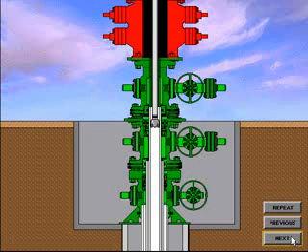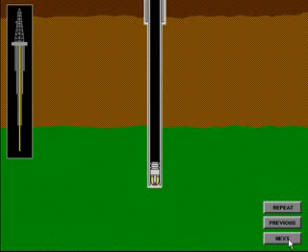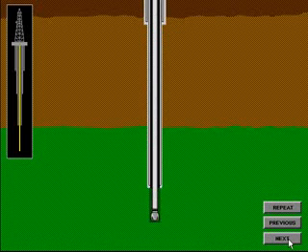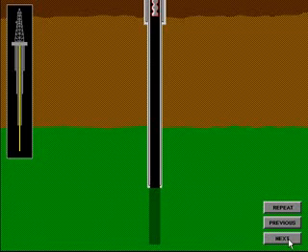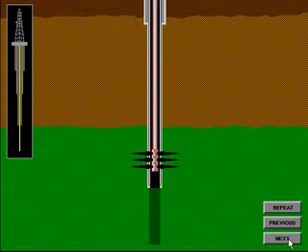Production tubing is considered any pipe string 4 inches in diameter or less, though sometimes larger sizes of pipe are used. When the plug has been drilled out and a cleanup trip completed, the perforating gun is run in the hole and the casing is perforated, or shot.